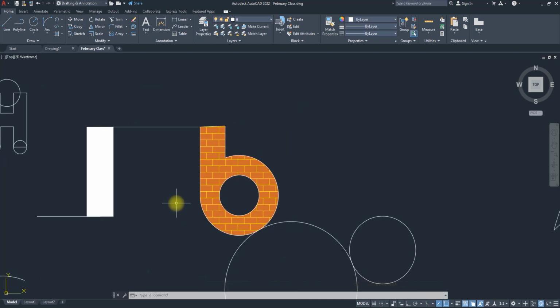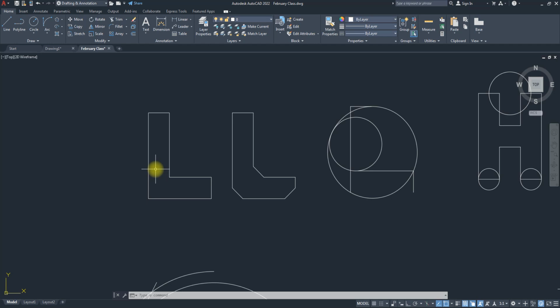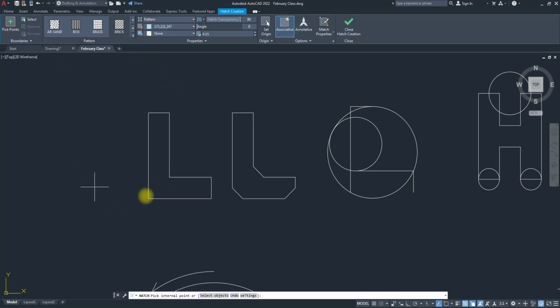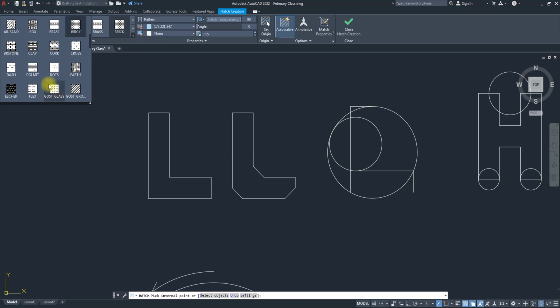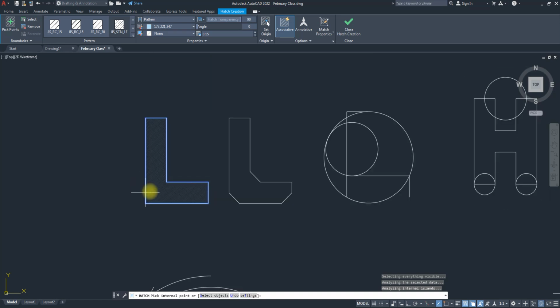Do you understand? But then you can still add color to your hatch. Do you understand? So if I want, for instance, to make this one, what's it called, a glass pattern, sort of, I can go to my hatch, look for glass, anything that I can use as glass. Glass is usually something close to this, so I'll select this as glass, fill in this shape. Now you notice the effect you have. This looks too dense. I need to scale it up. So I'll come to the scale, let's bring it up to 1.